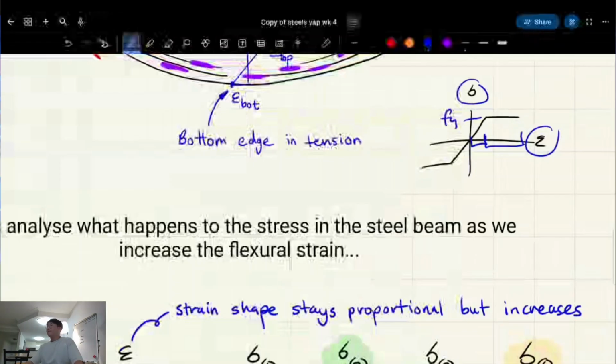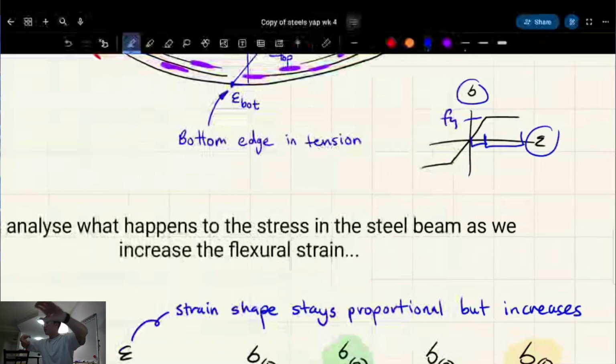So it's stretching, but the stress is not changing. The materials have a response. The resistance it gives for the strain will plateau out. It won't keep giving more and more resistance, like with a hydraulic machine, until it pulls apart and becomes broken.